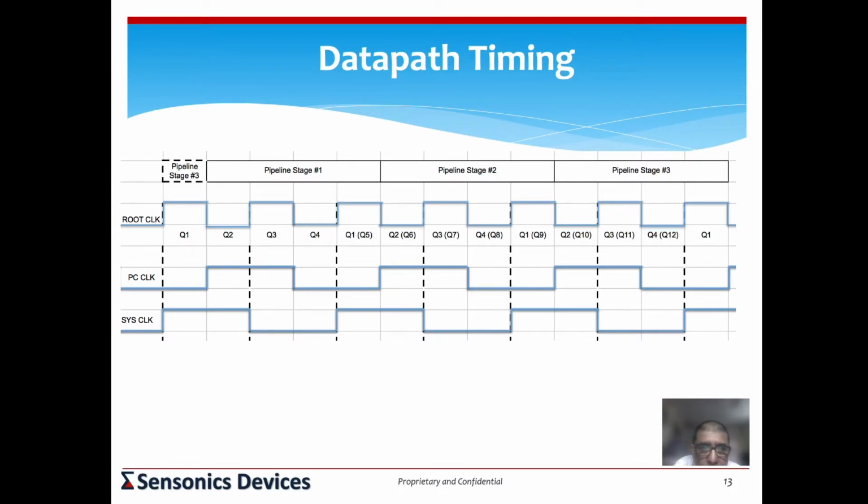And then what would happen is that the notion of pipeline might become invalid. You could have one instruction that runs for 3 quarters. There could be another instruction that runs for 4 quarters, and you could actually run your logic basis these durations in the pipe for each one of those instructions.